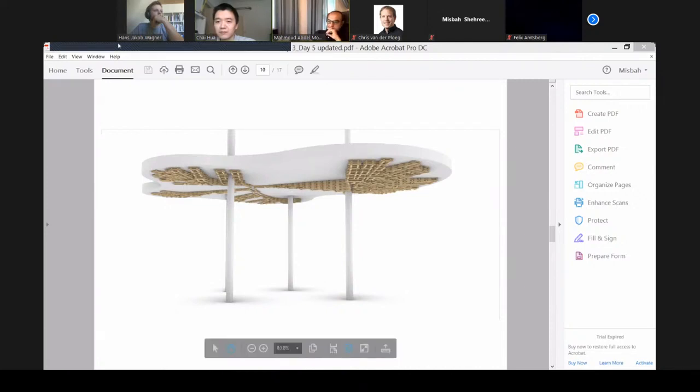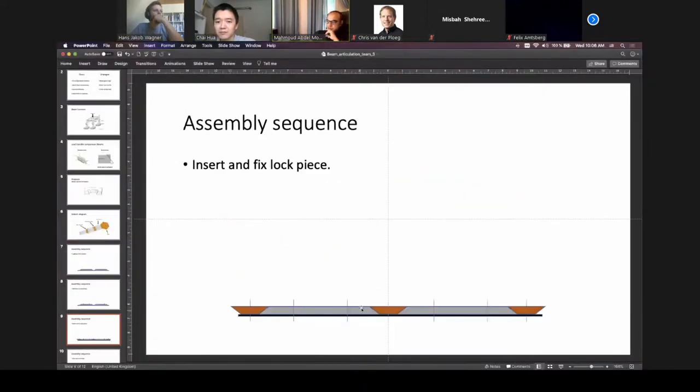I guess, in this case, when we lay them down in a straight condition, we could have a bit of tolerance, let's say 1 or even 2 millimeters, because once they are flipped around and start having loads, they will take this kind of sagging position, and in this position, they will just press and tension each other together, and they will hold together.